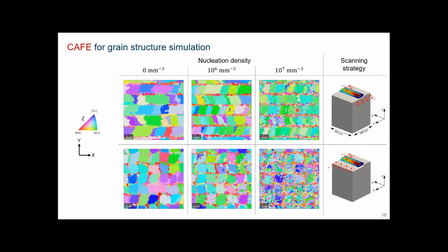Here, because you continuously bring new grains that are selected with their orientation, you have relatively fine grains in between. Here they are much coarser, because you only rely on the grains that were in the substrate. So then you have to study the effect of the density of the substrate, and you can also use a single crystal for the substrate and see what's going on if you have nucleation. This is what we did, but I don't show it here.